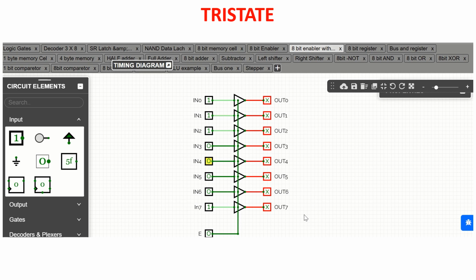In this way, the bus can be used to add a register. All the registers or elements not using the bus have to show a high impedance in order to free the bus, because imposing a 0 can create conflict on the bus if another register is putting its byte.